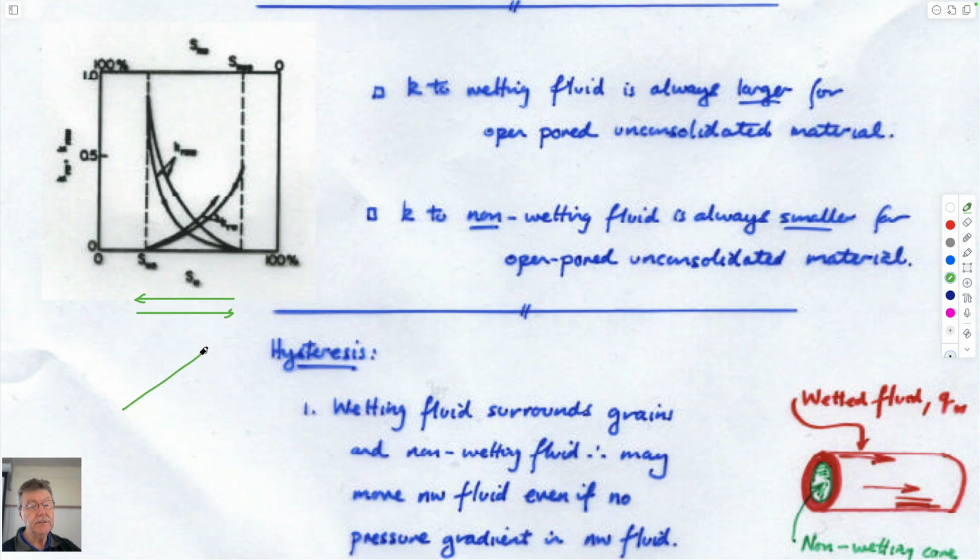And one of the reasons for that hysteresis is if you think of a drop of liquid sitting on a windshield that is trying to roll down that windshield, then the tail of that drop, which has been smeared as it moves down, has already seen a wet surface, and it is pulled across it. The front of this raindrop, as it goes down here, is seeing a surface that has not been wetted with water for the first time. And so the contact angle between these varies depending on the history of whether it's been wetted before or not.